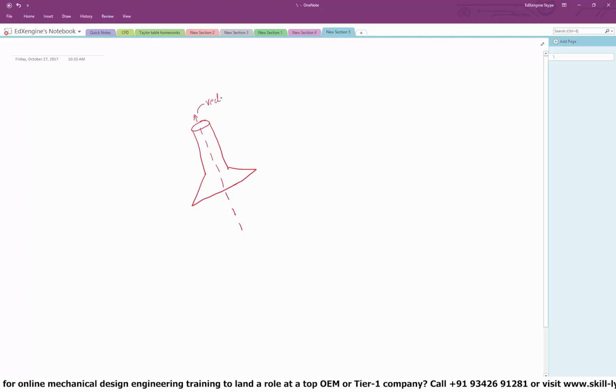So how do we determine this vector? If I zoom in into this area, and if I just draw that separately, you are going to have this particular face made up of triangles. Okay, so I'm just going to draw some triangles here. Each and every triangle has a normal direction, right? It has a normal vector. And as you can see, the direction of this normal vector and the axis of our valve are exactly the same. So at the end of the day, if I determine the normal of this particular triangle or even create an arc with the following points, then I can actually compute this direction.